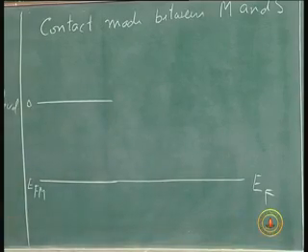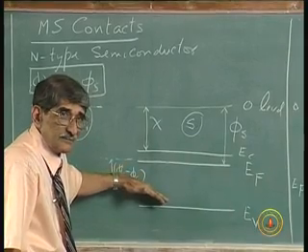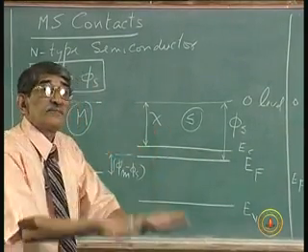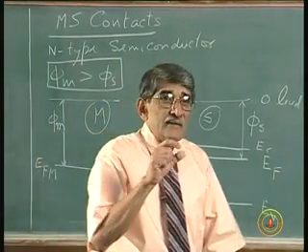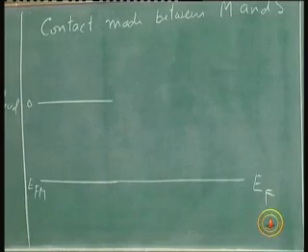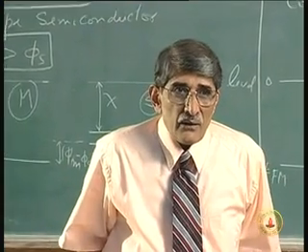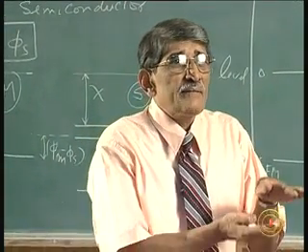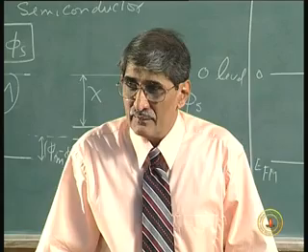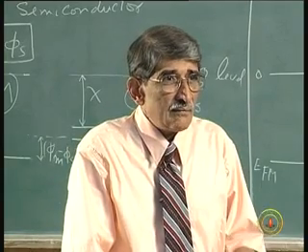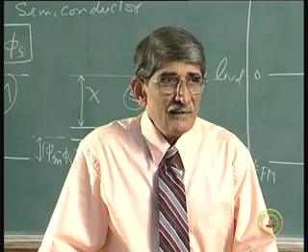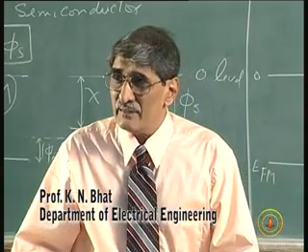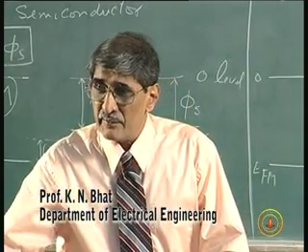So, what has happened is this Fermi level has come down, because electrons have got transferred from the semiconductor to the metal, leaving plus charges. Okay. Why do the energy levels go down now? See, whenever you have removed electrons from there, it is positively charged, and it becomes easy to transport electrons from infinity to that point.